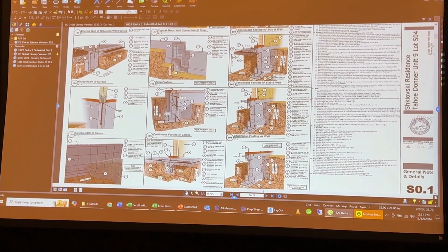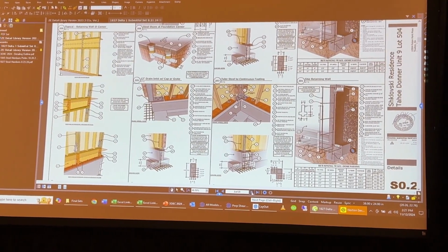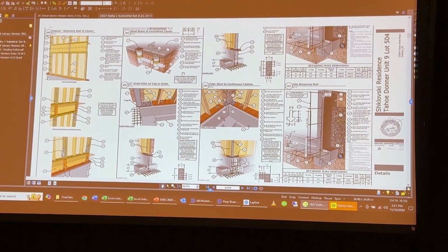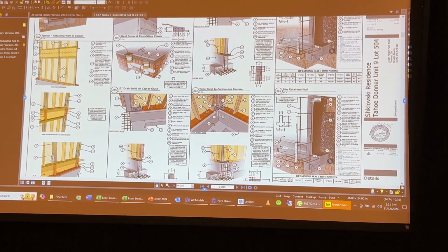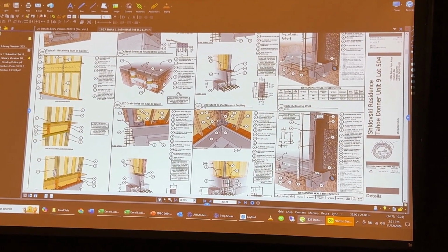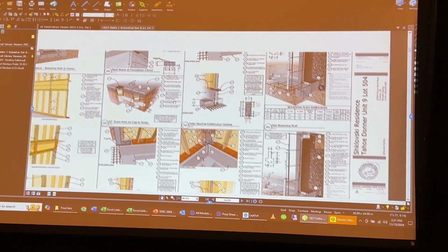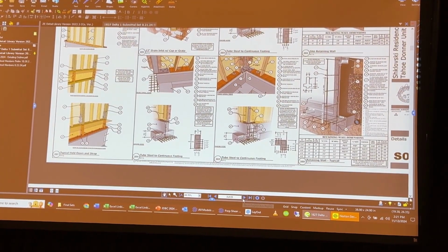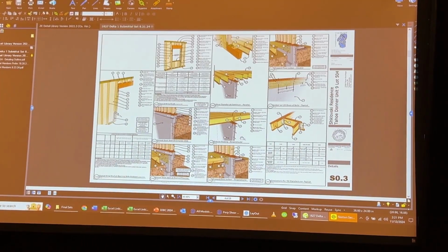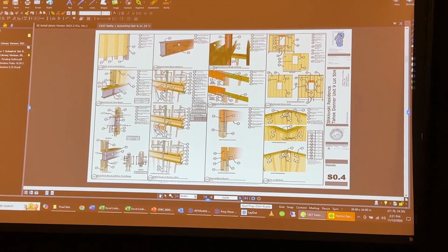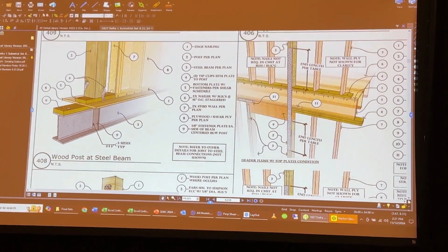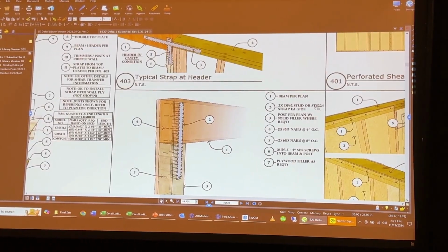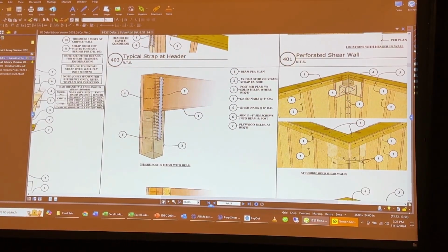So are you having to set the hyperlink for each detail? No, I do it in Bluebeam. It's a batch. I batch link it. Linking an entire set like that takes me 10, really 15 seconds. So if we find a Simpson product here, it's recognizing that actual 3-digit number. Here's a big example. PSB, Oslo, I don't have the old one yet, I'm sorry. It finds this, 6224.